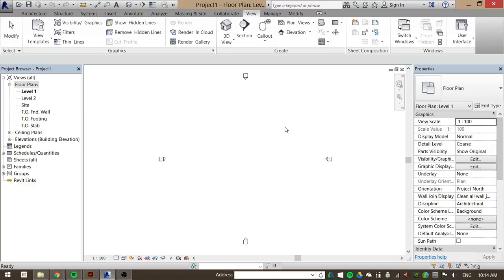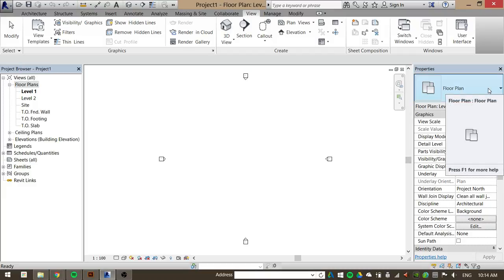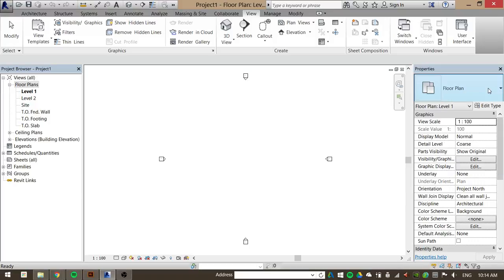If you place a basic wall in Revit, which we're going to do, and we'll get to that, this button here will allow you to select that object and switch it to a different type of wall. So instead of just a brick wall with 4 inches of bad insulation, you can choose a curtain wall, and it'll just change it automatically. It's super simple, super easy. It's not complicated. We'll get to it.